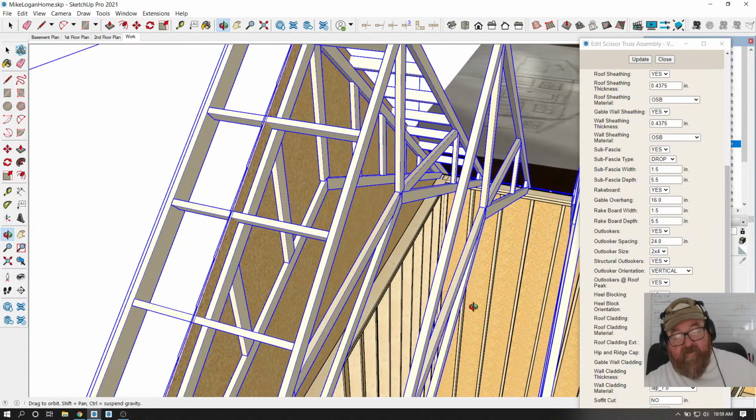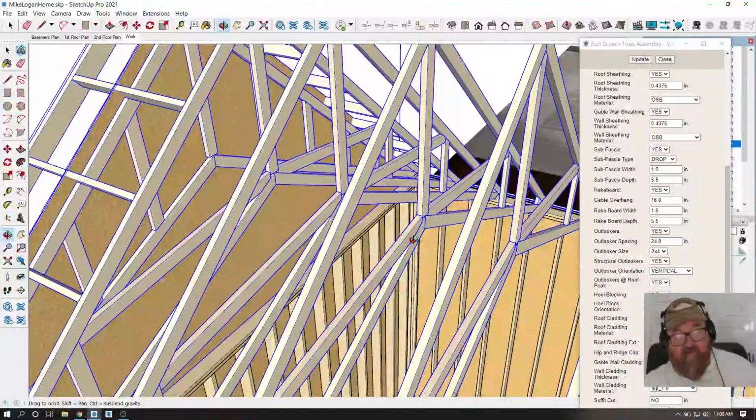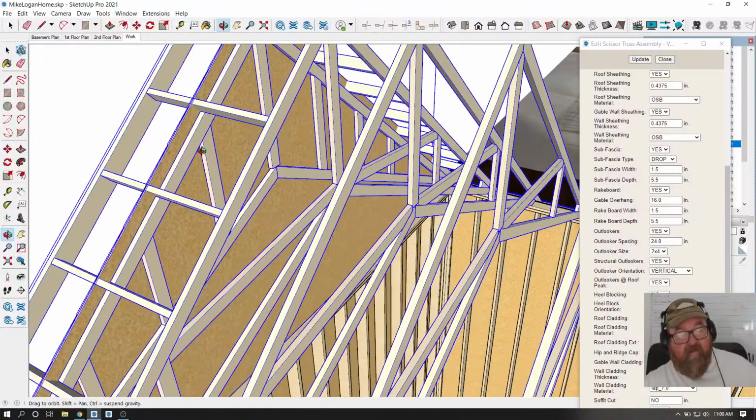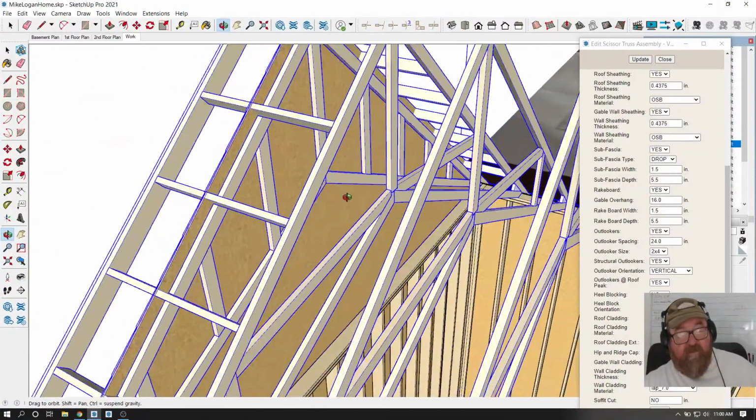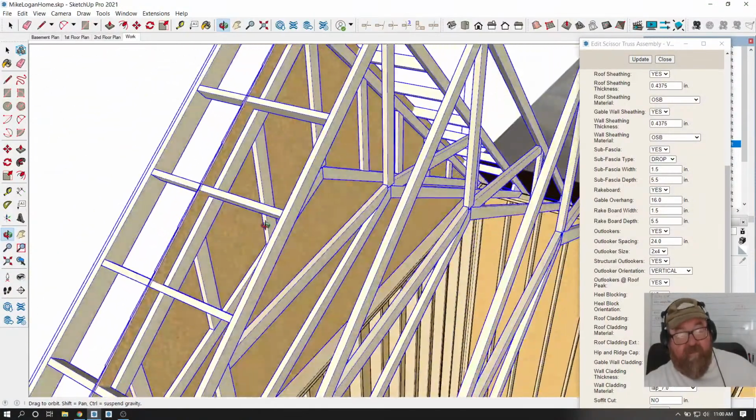Well, it's load bearing, it just doesn't have to span. It's open span like these others. So you don't need this particular webbing to resist those forces. So these gable studs can go all the way down.